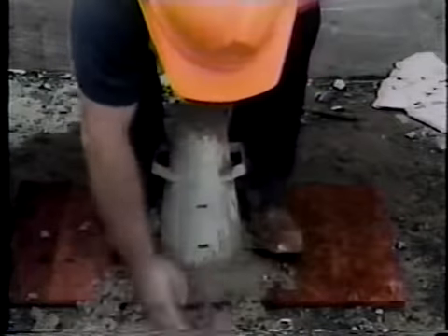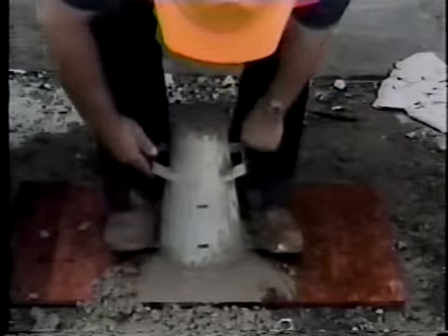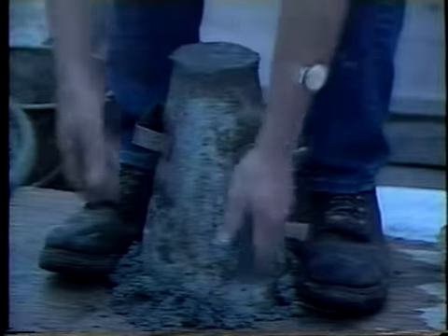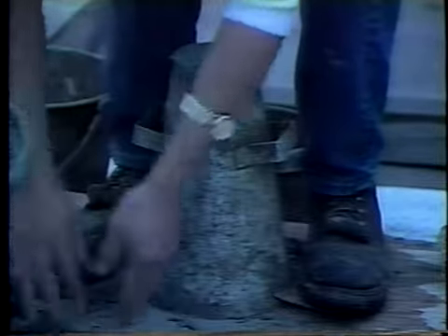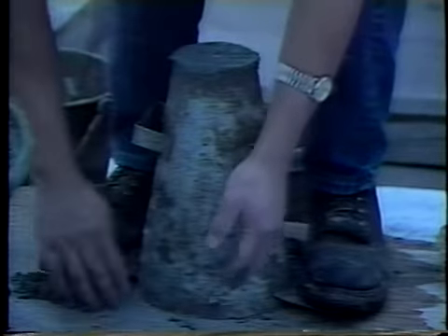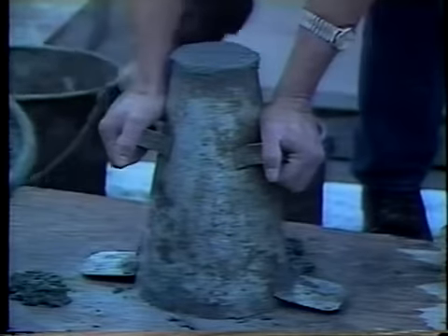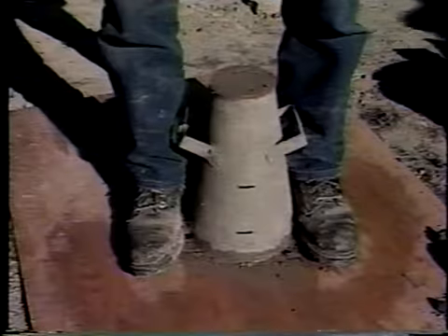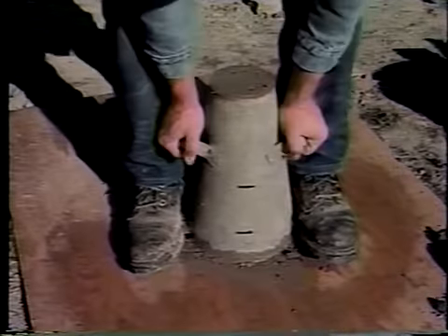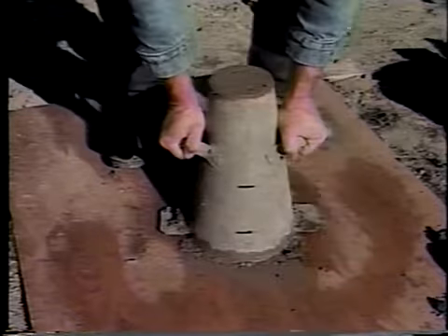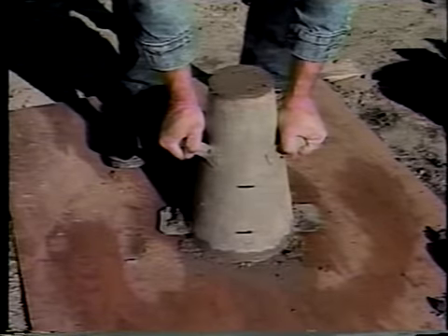However, the technician must be careful not to move the cone and disturb the concrete. Basically, both sides of the cone must be held still by pressure on either the handholds or footholds until the cone is removed. To remove the cone, both hands are placed on the handholds and downward pressure is applied to keep the cone stable before the feet are removed from the footholds.